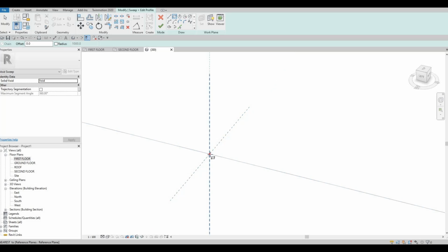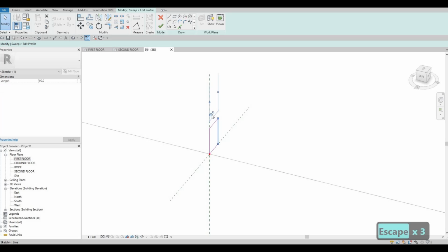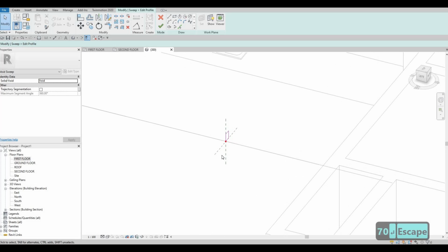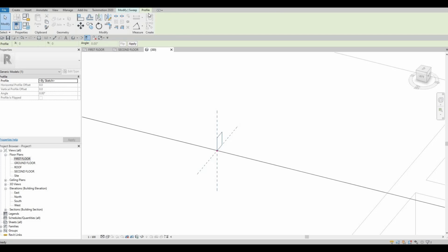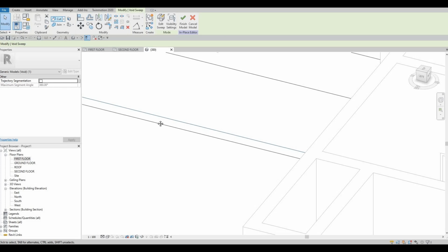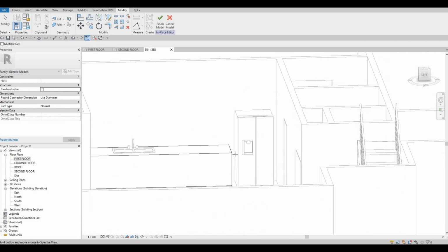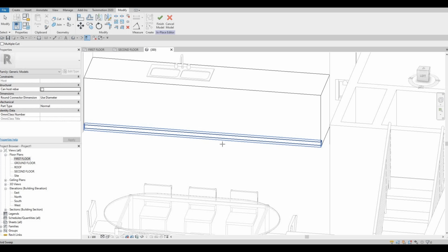And then now we set up our kick plate. So for me, I'm going to put this one around 50 by 70, or yeah, 50 by 70 is fine. We can even do 100, but that's fine. And then now select finish. Go back here, select finish again, and then cut geometry. And then we have our kick plate right there.